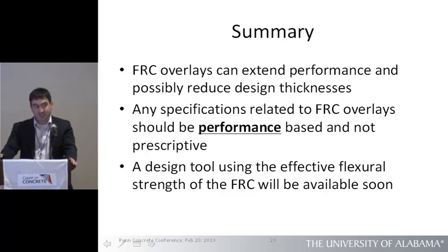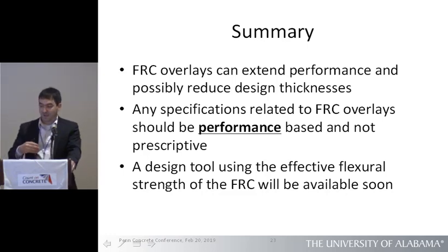But any specifications or any design that you're going to use should be performance-based, so following ASTM C1609, and not just prescriptive, like, oh, well, the fiber... wait, are there fiber manufacturers back there? Okay. They don't do this. At least the fiber manufacturers I know don't do this. But don't just blindly use 4 pounds per cubic yard because that's what the spec says the minimum value is. I know the fiber manufacturers would be happy to sell you more fibers, but whatever dosage gives you the performance you're looking for is what you should use. And each mix and each project is different.